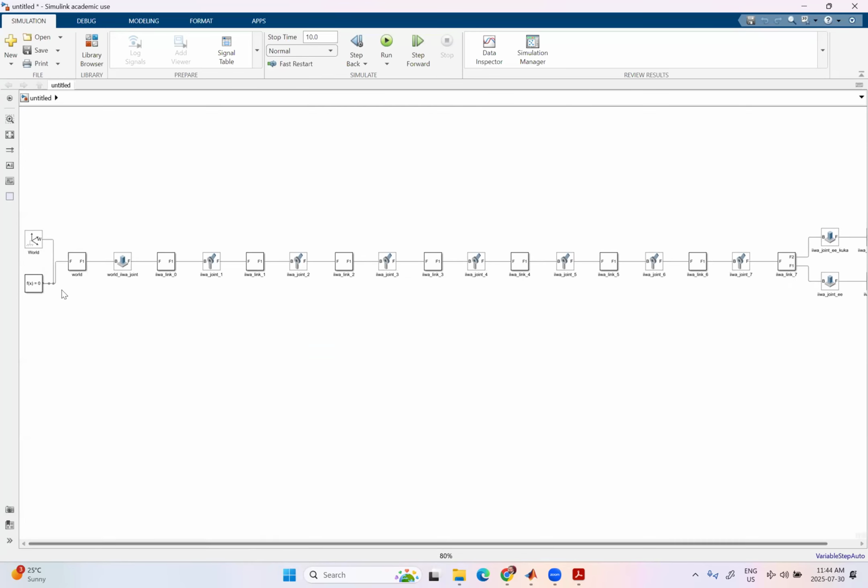You see a bunch of basically blocks: word block, function block, word block, and then a bunch of joints. These are from Robotics Toolbox, but these are already built. You can build your robot from scratch, or you have the URDF model and then you can bring it in. So what do you see? A joint 1, joint 2, and a linkage between joint 1 and joint 2.